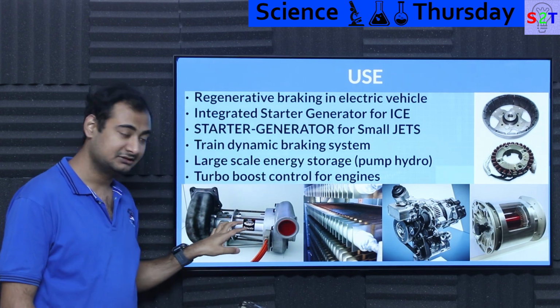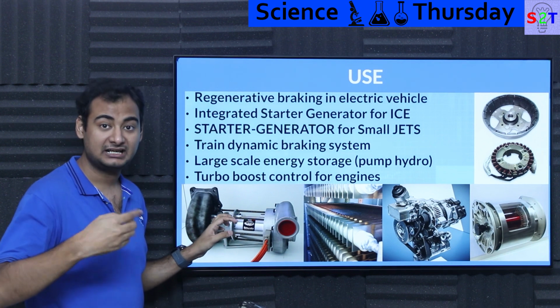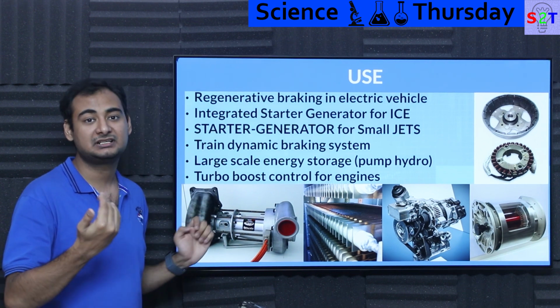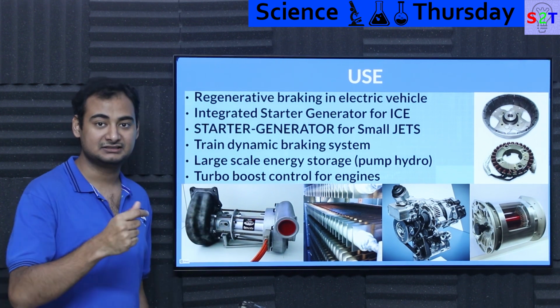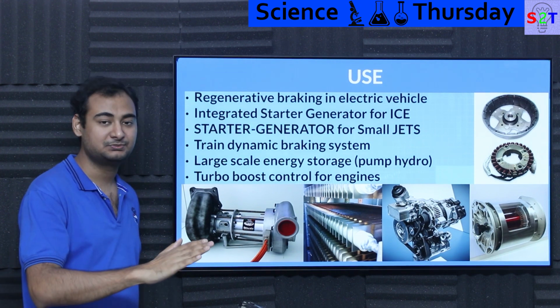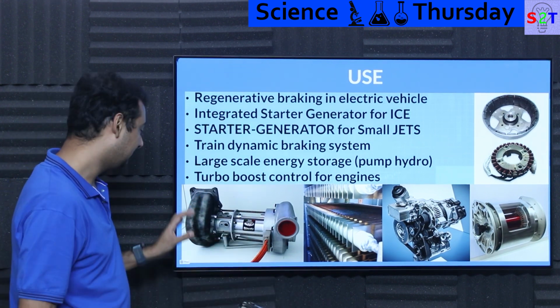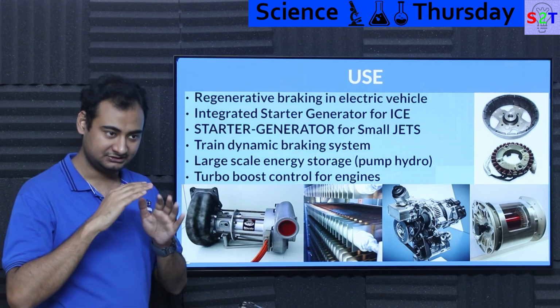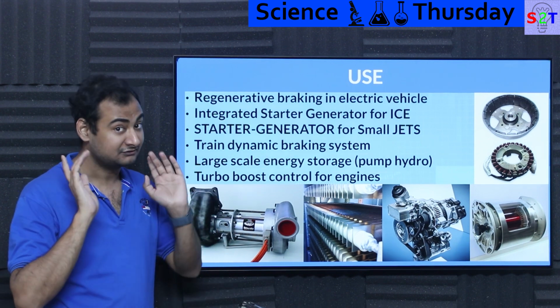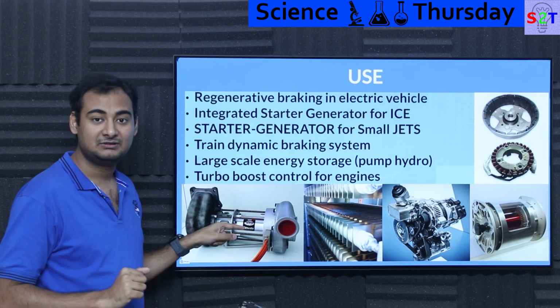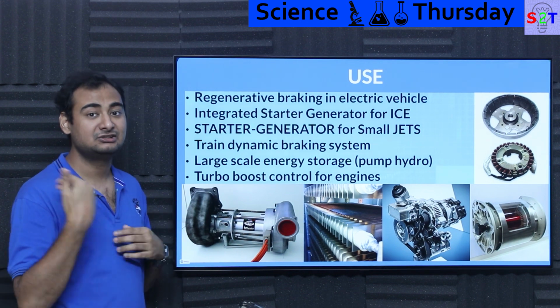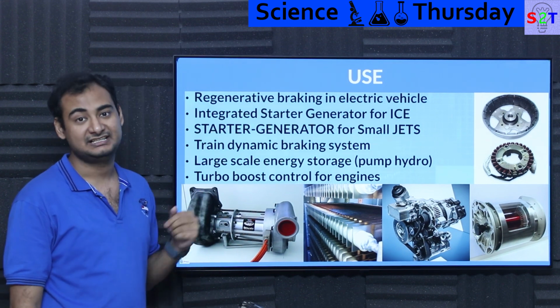So what this unit will do is act as a motor and spool up much more quickly. The exhaust will take, let's say, 2 seconds to spool up. This is like, I got this, half second spool up, done. So basically you press the accelerator, and your car is like, I got this. Now that's awesome, but you took the overtake, now there is a turn, now you have to slow down, otherwise you will crash. So this puppy will act as a generator, meaning it will start to sap energy away from the exhaust gases.